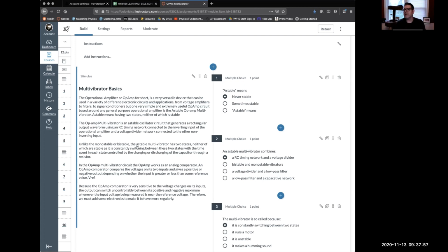You create an electronic circuit that basically has 2 ways of being. It has 2 states. When we did it with transistors, there were 2 transistors, and the transistors were coupled to capacitors. What would happen is a capacitor would charge until a transistor was tripped, and that transistor would then drive current to the other transistor, which would trip that one and cause its capacitor to charge. So you have these transistors that are activated or not activated. They're right on the edge, and it goes back and forth in a quasi-stable sort of situation.